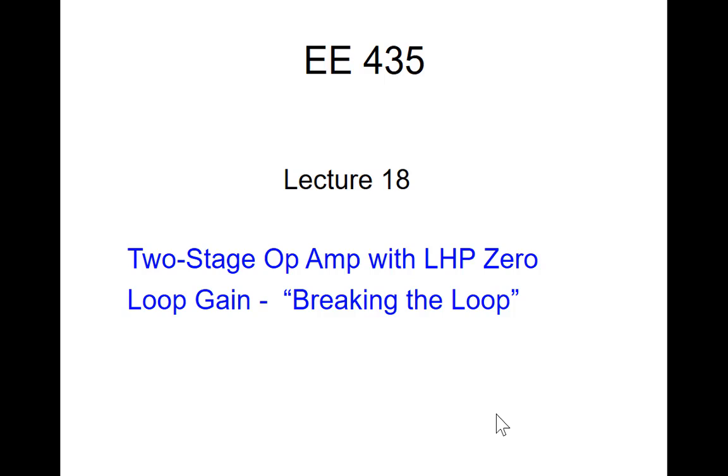So why do we use phase margin? Interesting about using phase margin: when you're done using it to do compensation, you'll typically do a simulation, and you'll typically find the performance is not what you want, even though the phase margin might be what you want.